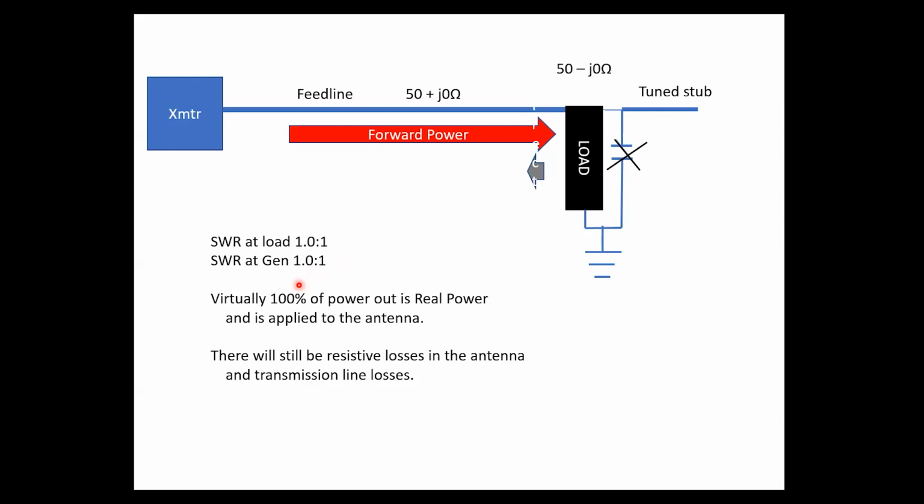So I'm going to have resistive losses in the feed line. Just because there's copper there, RG58 is going to have a lot more resistive losses than RG8. I'm going to have ground losses. I'm probably going to have some other resistive losses that occur as a result of, believe it or not, capacitive coupling between the legs of the antenna and ground.